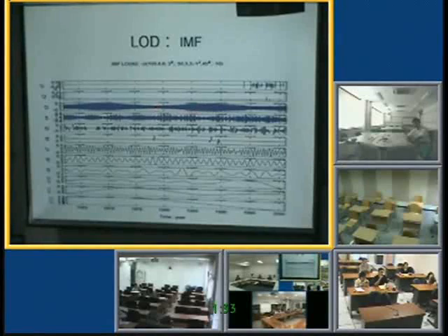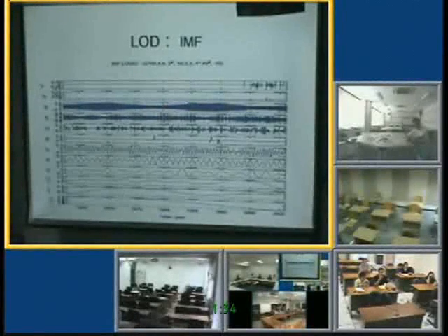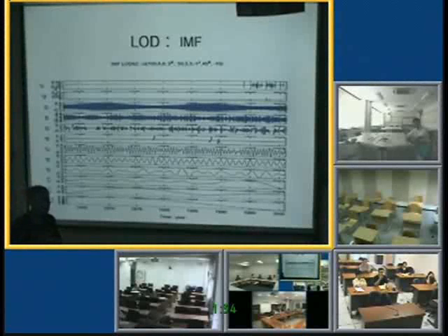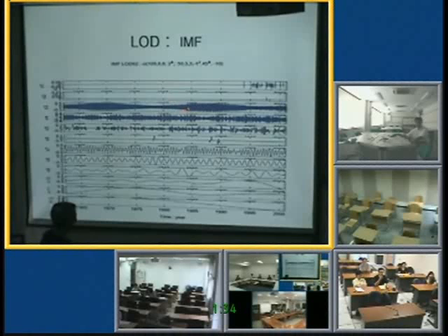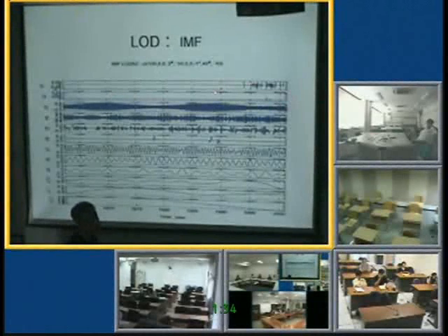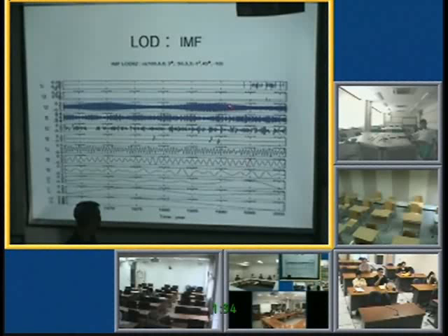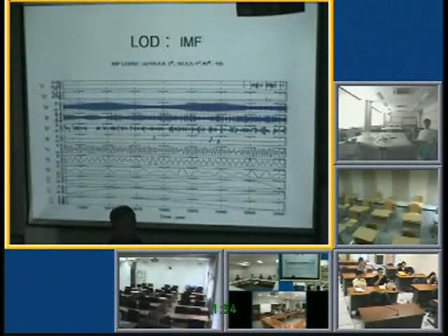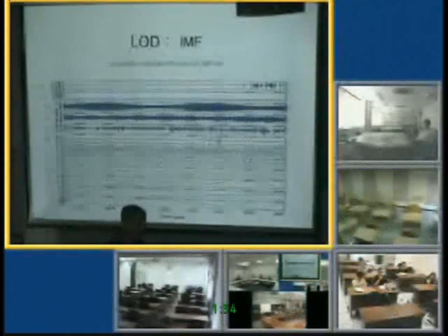Because that mode is modulated by the sun. It's a different time scale. Each component actually has two pieces of information. The first is frequency. The other is amplitude. These are FM and AM. The modulation actually is contained in the AM here, not the FM. Frequency is a carrier. So one thing we have to be careful about is that each component has FM and AM. Most of the time we emphasize FM and sort of neglect the AM. The AM is equally important. We'll touch on that.